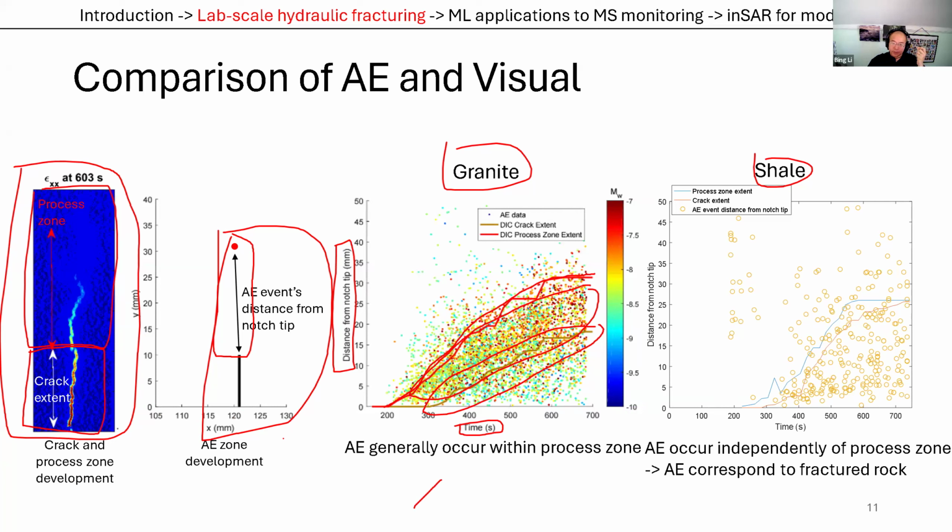That is, most of the events that we see, at least in the case of this beam bending, occur in the process zone and not in the area that's actually being activated, if you will, right? There's very little permeability that you get in a process zone because there's still some cohesion that's keeping your contact surfaces, or the surfaces of your crack, together.